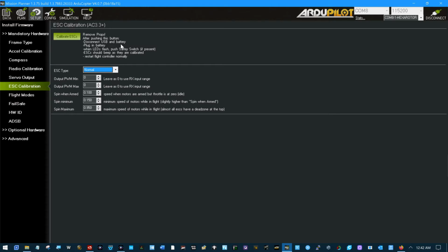If you don't power down the flight controller so that it can have that power up, so that it knows it's going to pass its throttle signal without modification, you're not going to succeed. So you can disconnect the battery all you want, but if you don't also disconnect the USB and let that thing completely power down, it's not going to happen. A lot of people get in trouble for that.